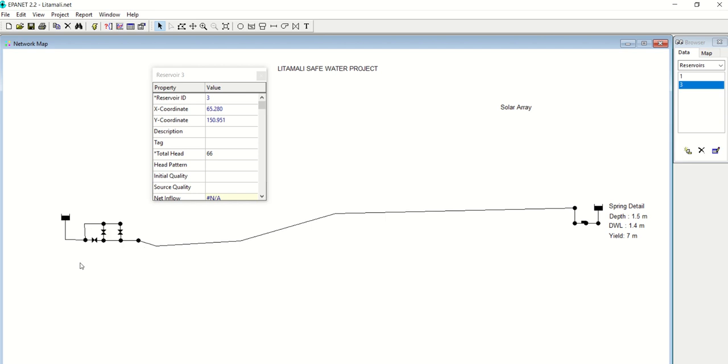So now this is how any system with multiple parallel chlorinators should be modeled. It has a bypass line, and it has the chlorinators going vertical, and it has a throttle control valve to control that flow. And the target will be 50%. Half the flow going straight through the bypass, and half the flow coming through the chlorinators and going in this pipeline.